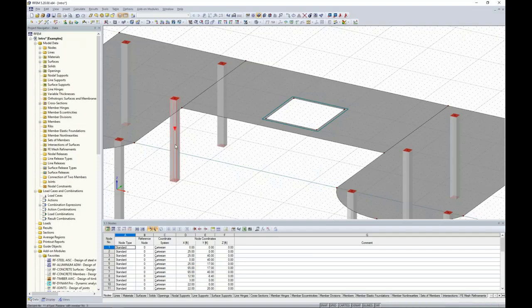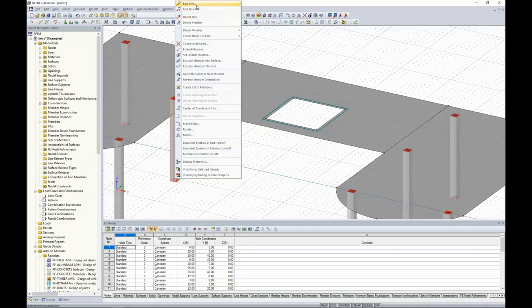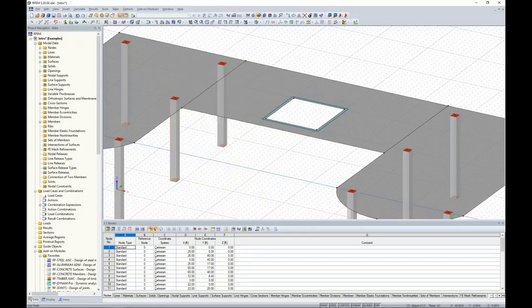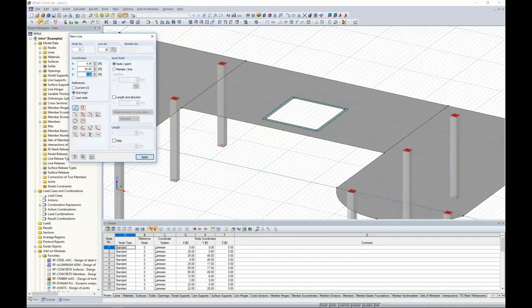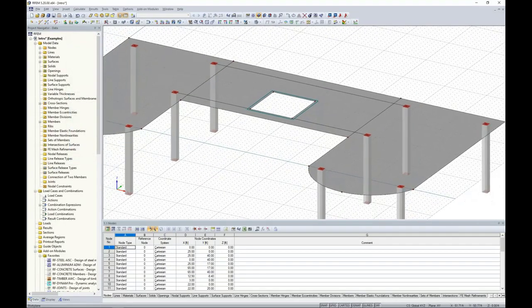So underneath every member is a line element, and we can see that when we right-click, we have the option to either edit the line or edit the member. So I can go back to drawing a new line, similar to what we saw before. This will just be a straight line, and I choose from the left column, and I snap to my right column. I right-click once, and I do the same exact procedure for my second set of columns here, and then I can right-click twice to exit that dialog box.